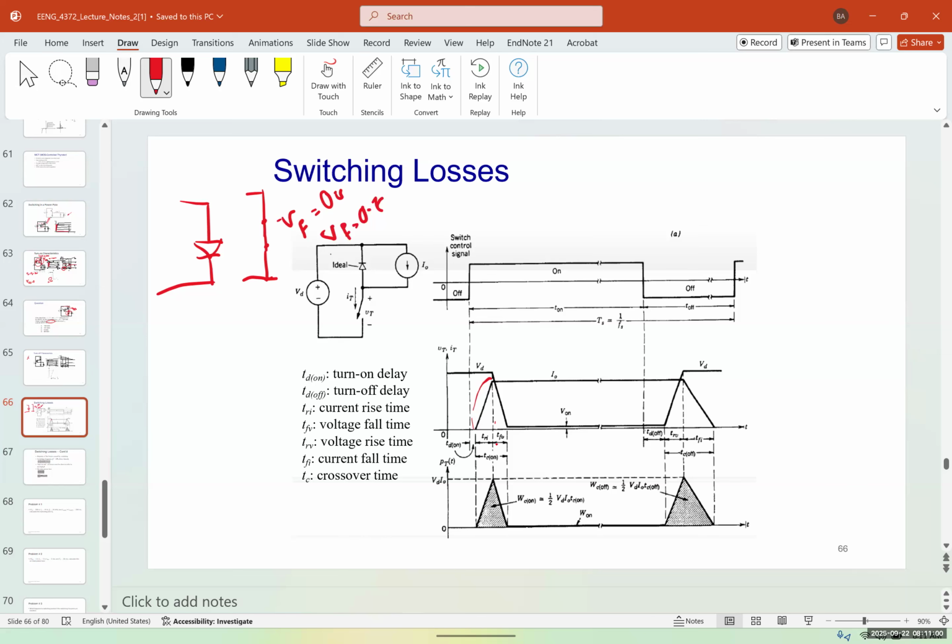So you can see that when the diode is turned off, because it's an open circuit, ideally, VD would be equal to Vmax. And when it's switched and turned on, it drops to almost 0. In the real world, you have a V on, which for a silicon diode is 0.7 volts.